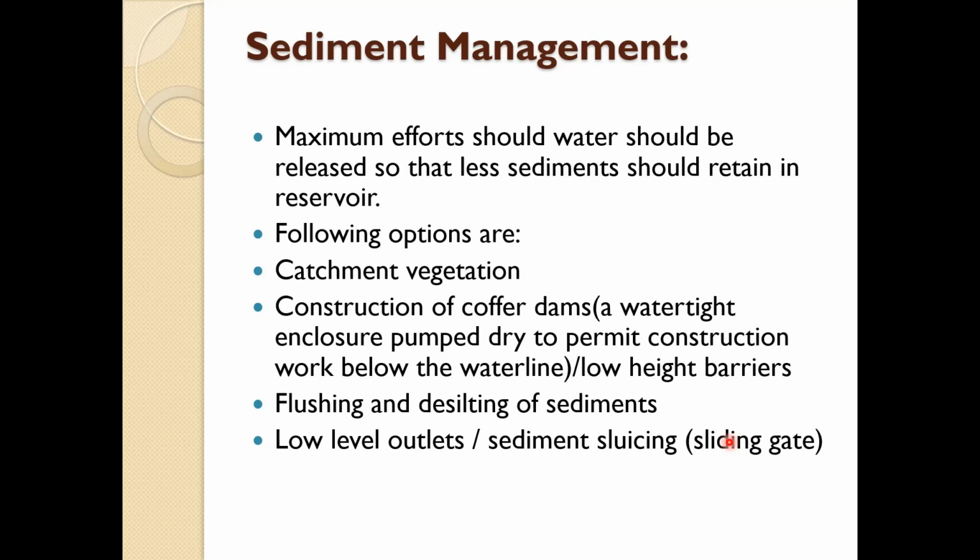Therefore, it is simultaneously supplemented with mechanical loosening and scouring of the neighboring sediments in order to increase the effectiveness. But providing large sluices near the bottom of the dam is again a structural problem, as we cannot provide a big size of these sluices at the dam. So the use of this method is limited.